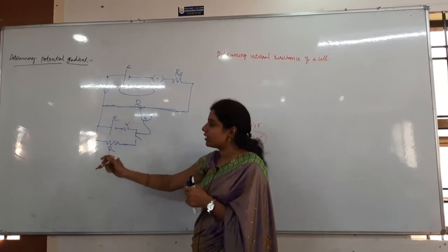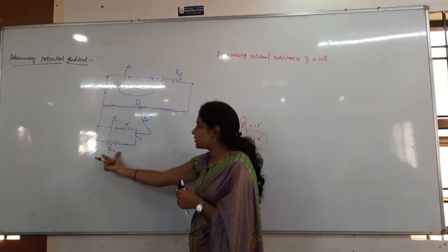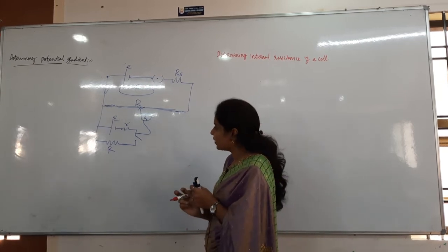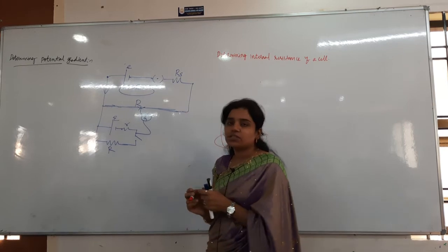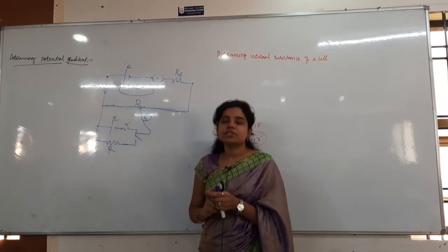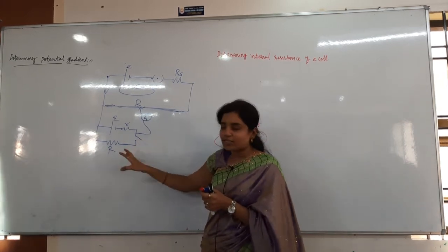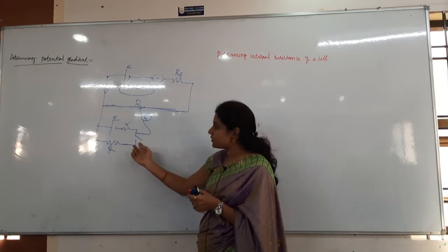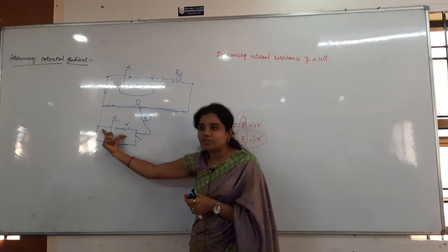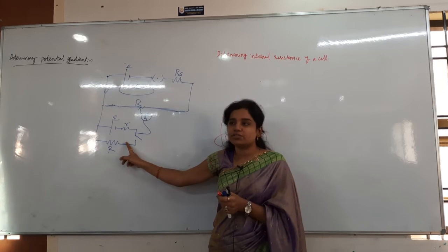In the secondary circuit, I have taken the cell of internal resistance r. That is connected to an external resistance, capital R, the load resistance. Whenever I open the switch, at that time what will be there, EMF or voltage? EMF. Why? Because the resistance is not connected. Whenever I open the switch, the resistance is not closed for this, so what will we draw from here? EMF only. Whenever I close the switch, what will be there? Voltage will be there. Clear?